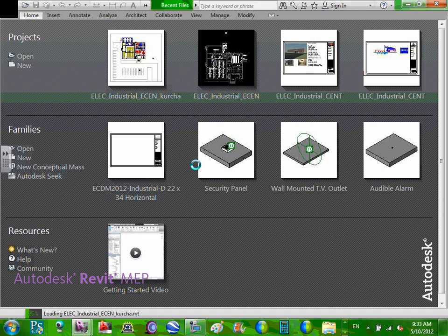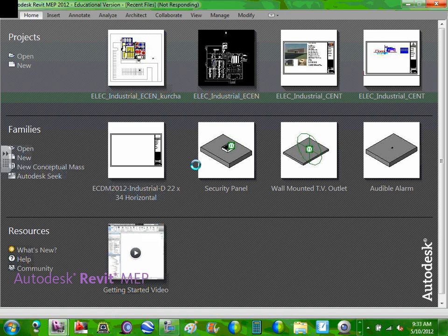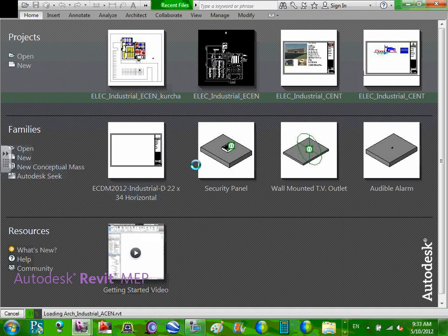So you have a large open area then that's open to the structure? Yeah, well, the challenge with this model is there are multiple levels. There's manufacturing floor that goes from the first floor all the way to the roof. And then when you cut, wherever you cut, you're going to see certain things. So you probably want to use a filter of some sort. What we did in the past, you weren't here when we did the Revit, is if we see them in the second floor, we just go hide in place and hide them and call it a day. That's kind of how we solved it. Yeah, that's the poor man's way to do it, but that's a way to do it. A lot of times with Revit, it's honestly just figuring out a way to make it work, and then you sort of move on.